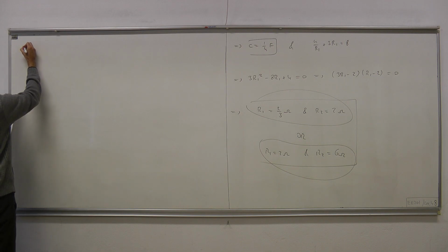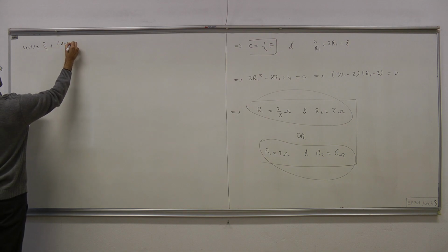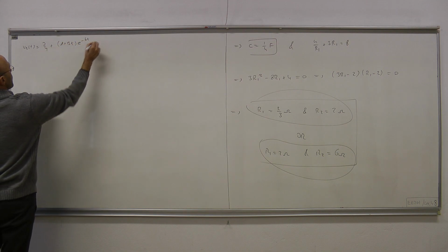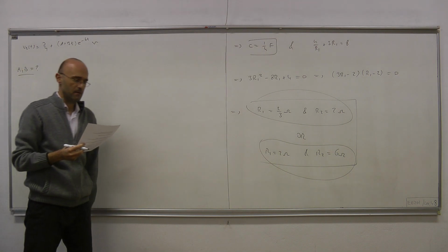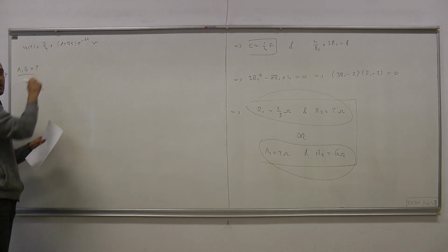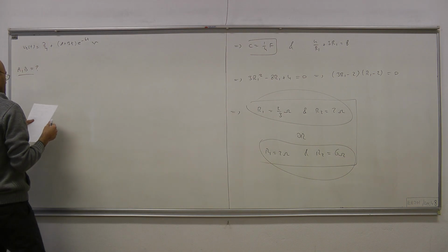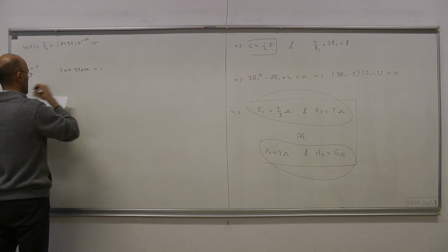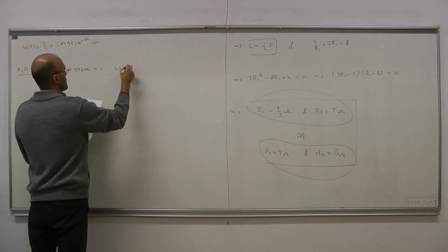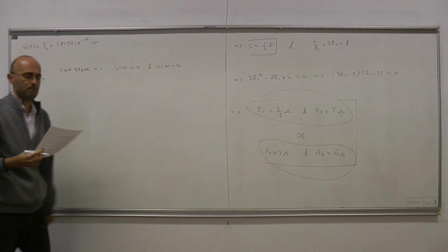So what we have is V2 of t equals 3/4 plus A plus Bt e to the minus 4t volts. Okay. So the question now is, what are A and B? Now this is step response. Therefore, by definition, we're talking about a zero state situation, and that means IL(0) equals 0 and VC(0) equals 0.